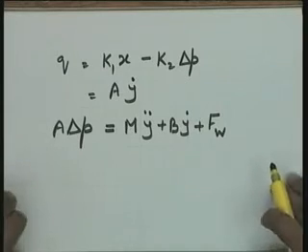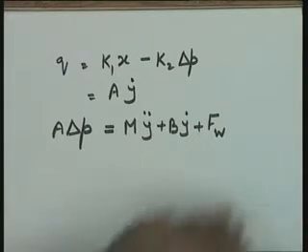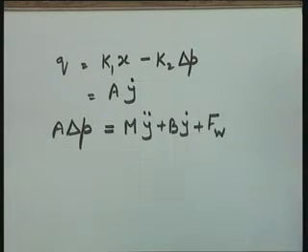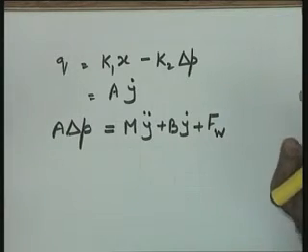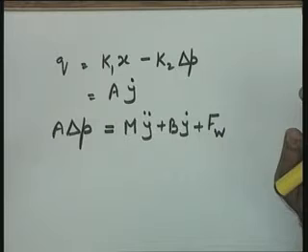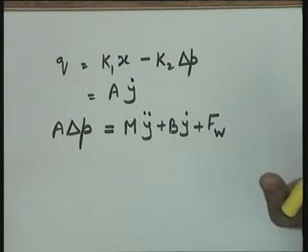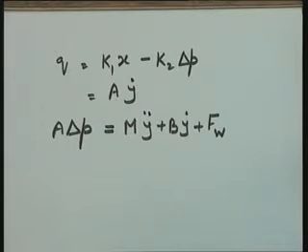Okay? Fine. Now please get me a transfer function. Once this information is available, you are equipped now to give me the transfer function. Keep in mind, my interest is in two variables, x and y. X being the input variable and y being the output variable. X will become my manipulated variable when I put this linear actuator into a feedback system, and y is the controlled variable of the feedback system.